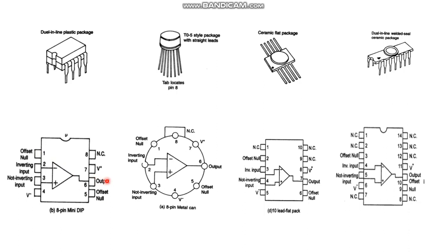We have to null that offset, that is known as offset null pins. Okay, by applying some offset voltage, you can nullify the offset. Offset means without input we will get some output voltage. That output voltage is nothing but offset. Okay, and these are the different packages.